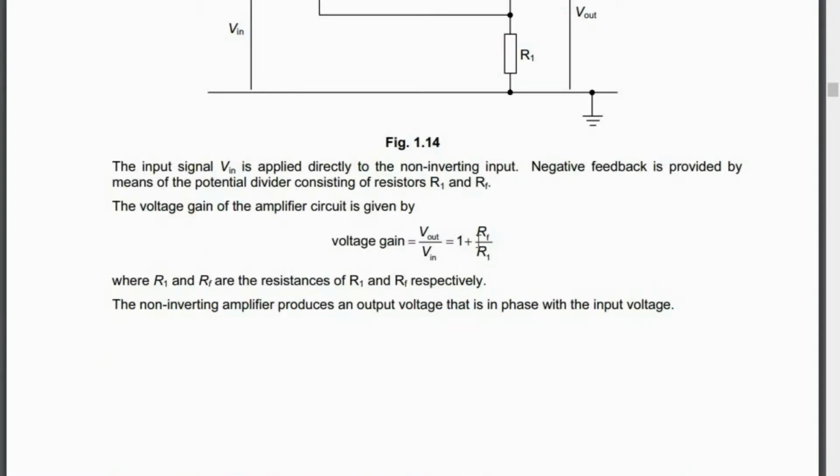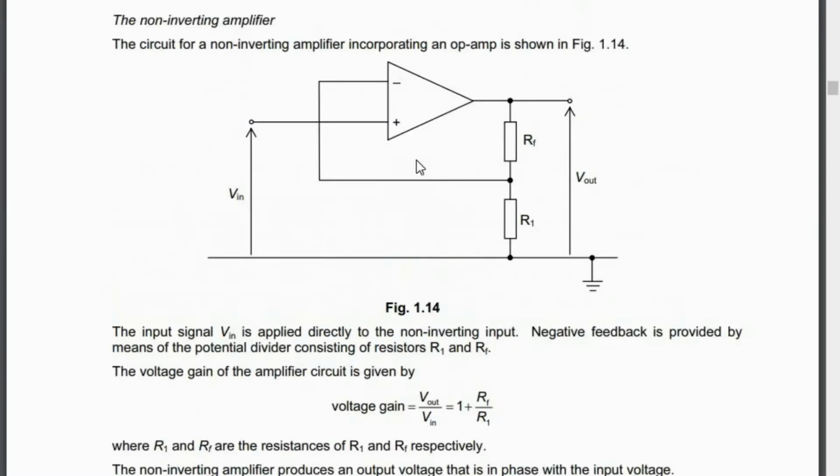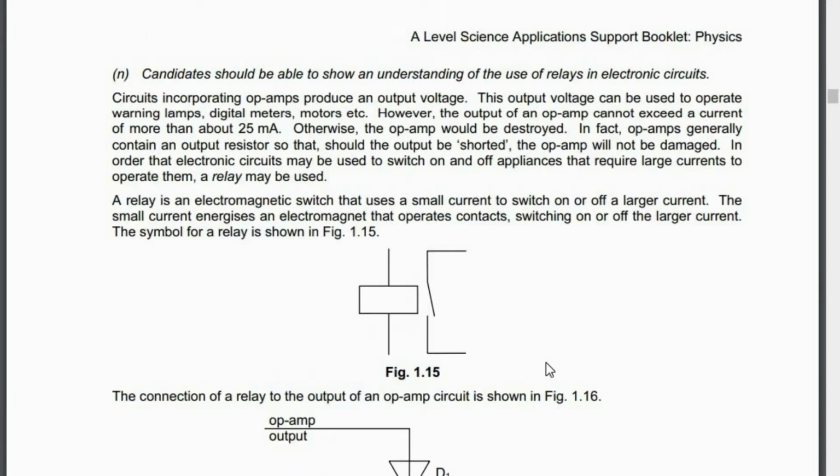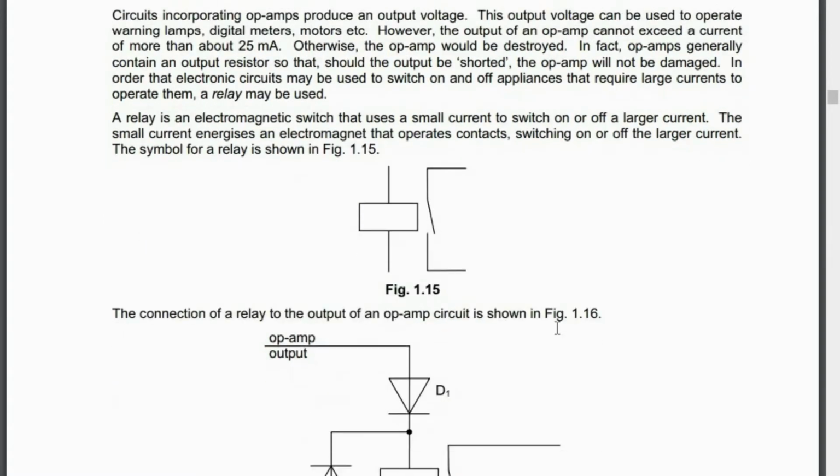So look here, there is no multiplier with minus. Why? Because the input is to the non-inverting input. Whatever comes here will be positively amplified. That's it. And again, it's the same concept. The higher the feedback loop resistance, the higher the gain. Is this clear? Guys? Everyone? Okay. Then we can talk about the possible outputs. We're going to talk about two different outputs. Okay?